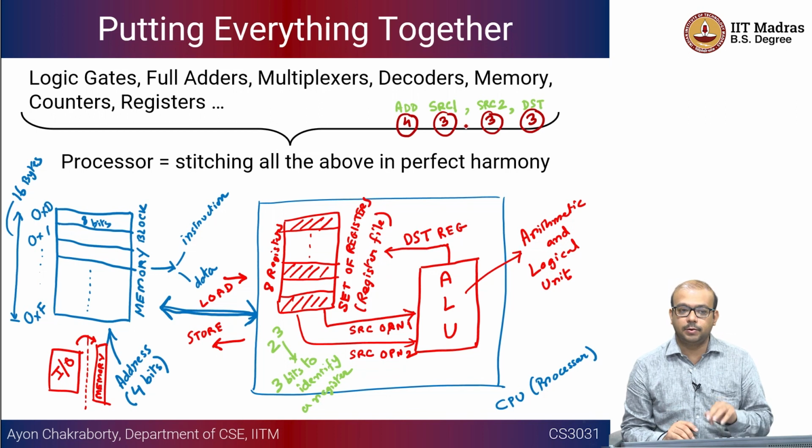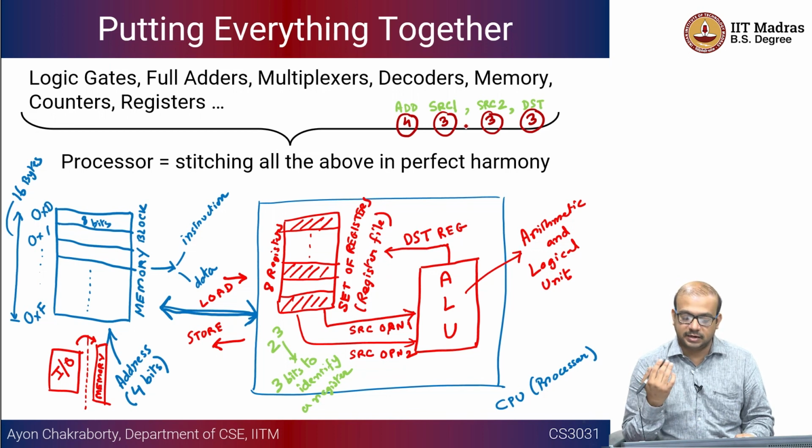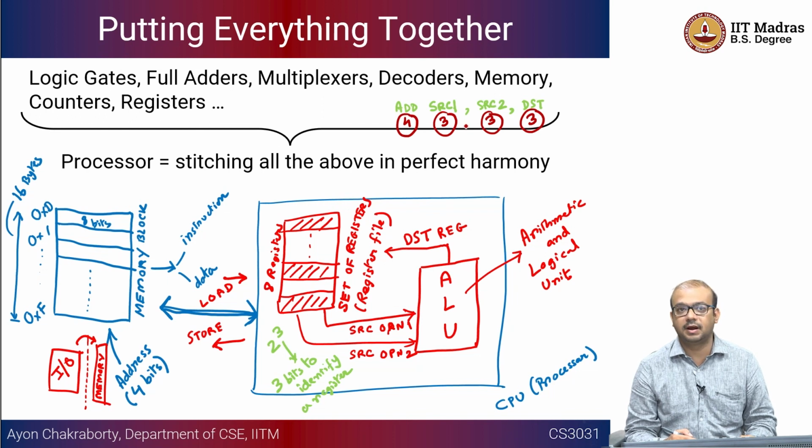There is a lot of assumption here. The assumption is that you have this many instructions and this many registers inside, right. If you have, let us say, 32 registers inside, I need 5 bits to specify a particular register. So, just for expressing SRC1, SRC2 and DST, I need 5 plus 5 plus 5, 15 bits, right, because 2 to the power 5 is 32. Here I have 8 registers, so I need 3 bits. Okay. So, now you can understand why giving more flexibility inside the instruction itself is also expensive in terms of encoding the information that is contained in the instruction. Okay.